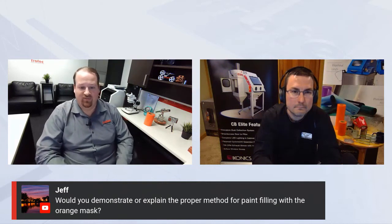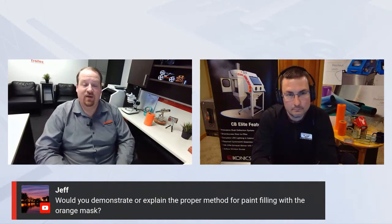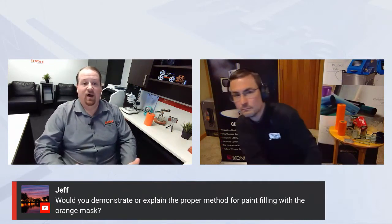Okay, next question. Would you demonstrate or explain the proper method for paint filling with the orange mask? Well, we're not going to be able to really demonstrate it. We're not set up to do that. But ultimately, if you were to use it with the laser system just for paint filling instead of sand carving, the process would be just the same that I went through and showed you on the video. Apply the mask, peel it off, engrave it through into the material, whatever that material is. And then instead of taking it to a sand carver, all you would do is take it to your painter. Make sure any excess material, exposed material, has been masked off. And then go ahead and paint it, let it dry, and then peel the mask off to expose the finished painted object. So yeah, it would work just as well for that.